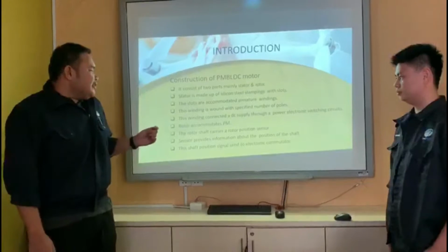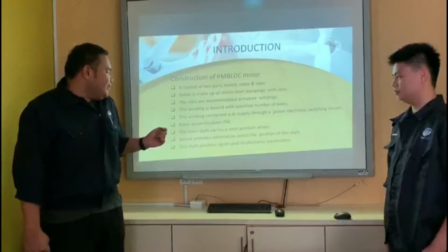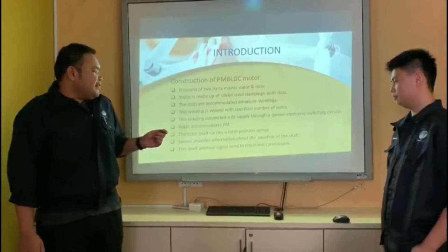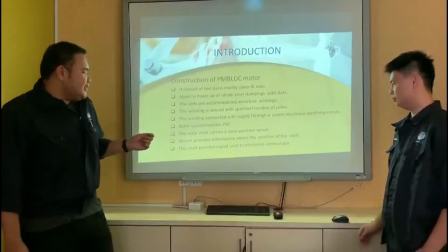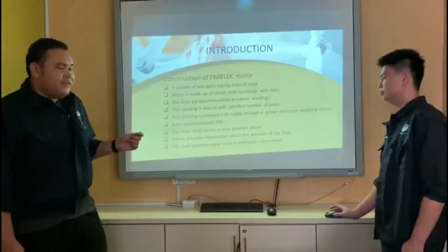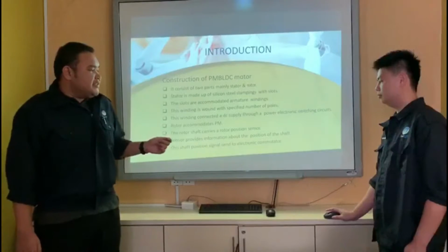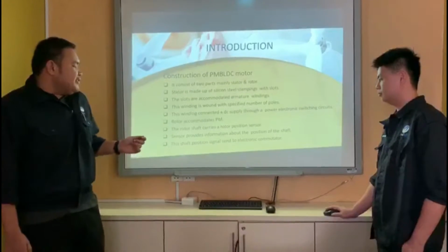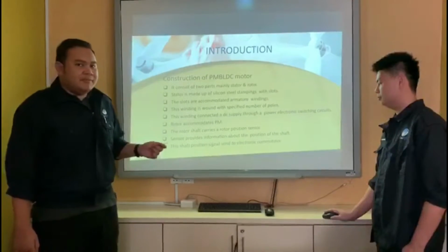The rotor accommodates the permanent magnet. The rotor shaft carries a rotor position sensor, and the sensor provides information about the position of the shaft. This shaft position signal is sent to the electronic commutator.